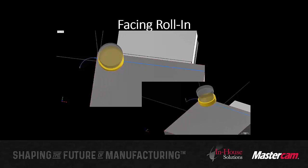It's a little more desirable for the tooling suppliers, what they suggest in terms of a method for entering on a face mill toolpath, and just a little less harsh on those inserts. So if any of you are dealing with any harder materials, any of your Hastelloys, stainless parts, and chipped cutters, chipped inserts are something that you're constantly trying to avoid and constantly battling with, this may be something to look into.